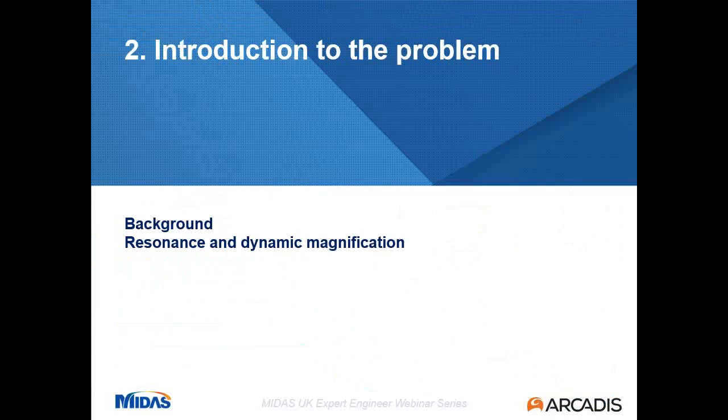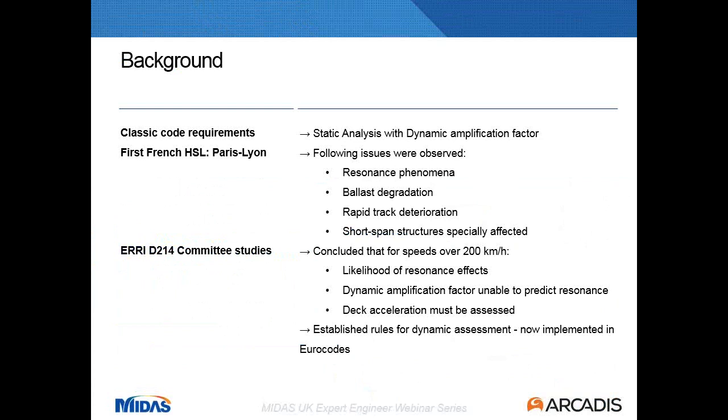Now that I have introduced the scheme, I'm going to introduce the problem. So what's this problem of resonance and dynamic magnification? Well, the classic approach of designing bridges is to use static analysis, where you analyze forces and deflections in your bridge under certain loading, and if it's a rail bridge, then you will use maybe a moving load to check different positions on the train.